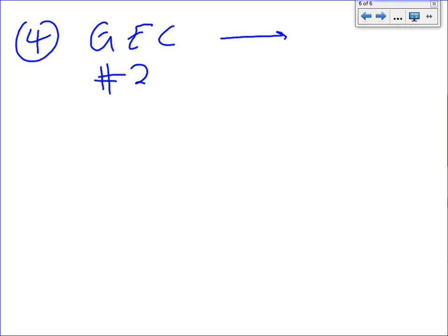Okay, number 4. What did we say number 4 was? Grounding electrode conductor. The conductor was number 3, so you take number 3 to Table 250.66. I hope I've repeated myself many times, guys, so it sticks, because this is over and over. We'll keep sizing up. Number 6, number 8.